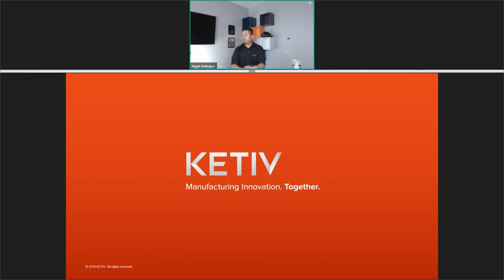Is the symmetry plane step required? So no, it's not required, right? You don't have to add a symmetry plane if you don't need it. In addition, you can add multiple symmetry planes if you want. Obviously, you can't have 2 symmetry planes that are parallel to each other. That doesn't work, so keep note of that. You can have symmetry planes that are in perpendicular directions. That makes sense.